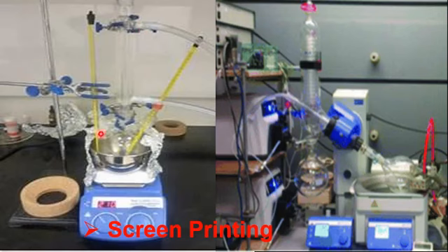The films deposited with the chemical solution based deposition techniques like sol gel, co-precipitation, micro, screen printing, or spray pyrolysis are less costly because they don't need a vacuum environment.